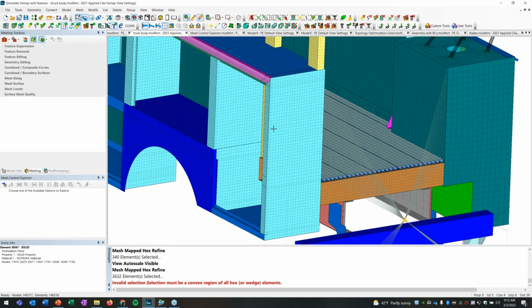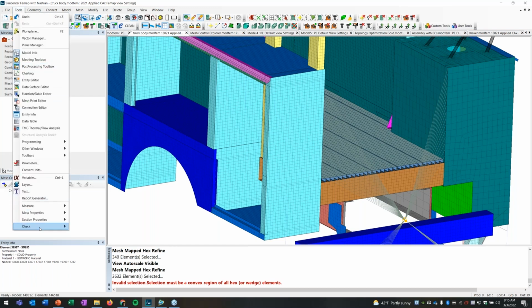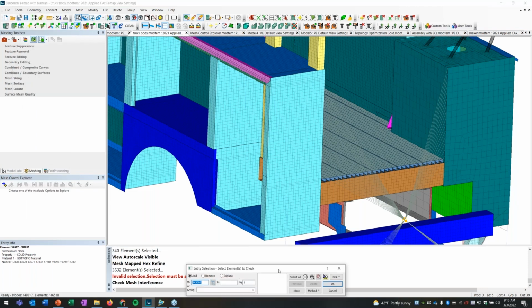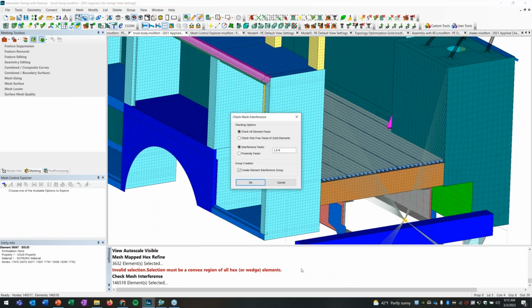It's always a bit hard until the analysis is actually done to know what your initial and deformed gap separation or contact separation gap was. But now there is a pre-processing tool under check mesh interference, that helps us find this here.